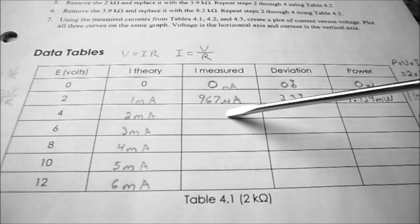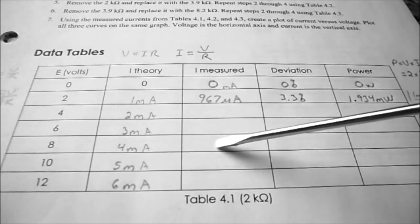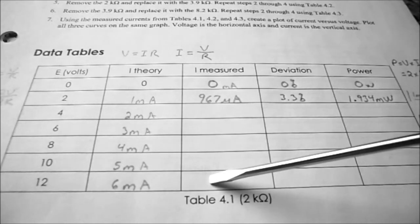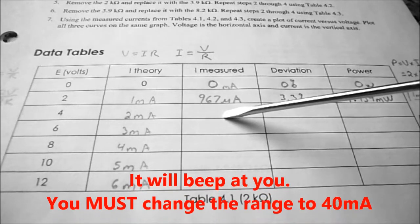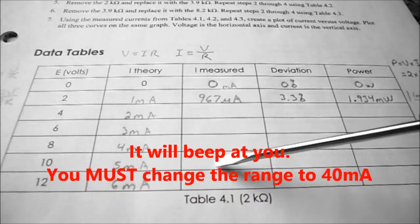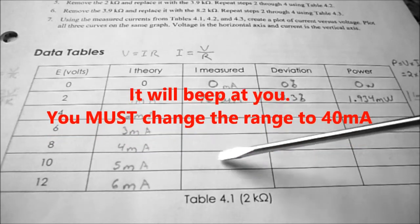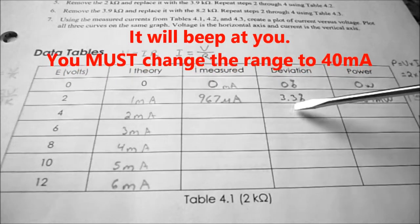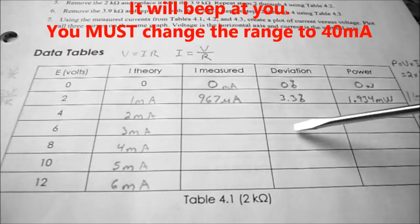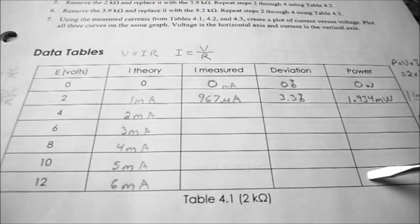So you just need to increase the voltage on the power supply. That's the plus 20 volt terminal. So increase it to 4, 6, 8, 10, and 12 volts. And remember, you may need to change the range setting on the ammeter if the current actually goes above 4 milliamps. I'm going to leave you to calculate percent deviation and power dissipated by each of the resistors.